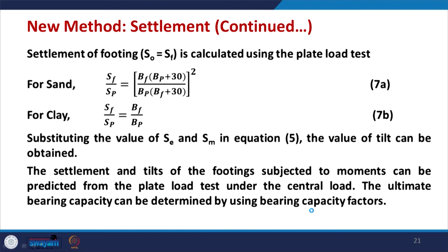The settlement of the footing, which we call S naught in this method, is nothing but SF, the settlement of the footing, and this is calculated using the plate load test. We have already discussed the plate load test, and as discussed earlier, for sand you have a relation between the settlement of the footing divided by the settlement of the plate.